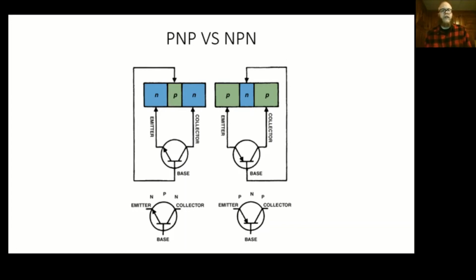The thing that's cool about this, though, is I'm going to put like 5 milliamps, 0.005 amps here at 0.6 volts, and that will allow 100 times more amperage, so that would allow 500 milliamps, or half of an amp, of current flow across my collector and my emitter.